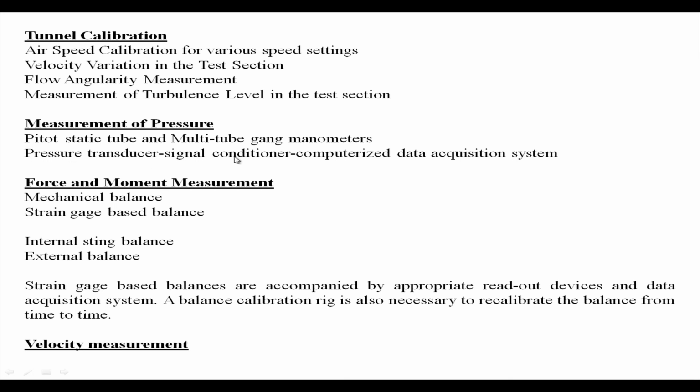Pressure transducers, yes, the answer must be coming from that end, but then again you have a whole lot of variants and you need to pick and choose the correct one for your application. Scientists from different labs know very well that you may choose a conventional transducer like the ESP or Scanivalve pressure scanners for some applications, but you may choose to use Kulite pressure transducers for other applications.